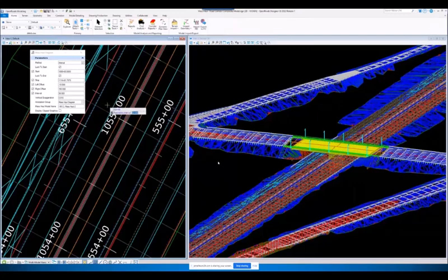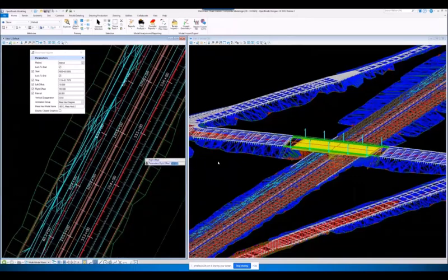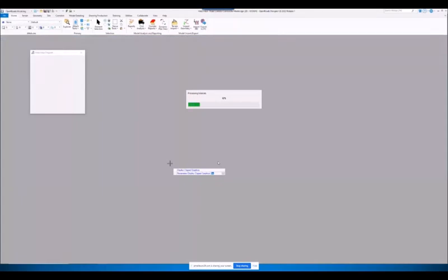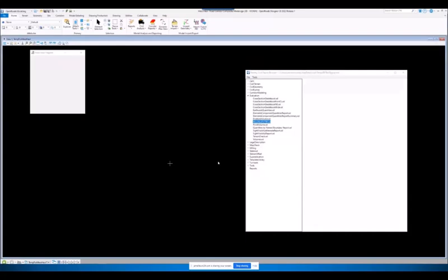And you can see I'm going to start looking at the parameters on how frequently I'm going to do the analysis, every 50. I'm going to look 10 feet to the left, just in the middle of the median, the side I can move the dirt, and we're going to look to the right side, to the northbound lanes, 150 feet. That's the only area I'm looking at the cut fill, and I'm clipping the three-dimensional model to determine how much cut fill I have in each of those sections, so I can figure out in that range to plot that under the curve for the mass haul diagram. And that's what we're doing with that. So we're looking at, again, the 3D model to do this.